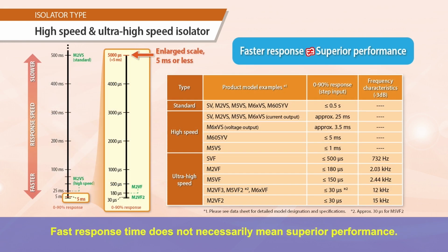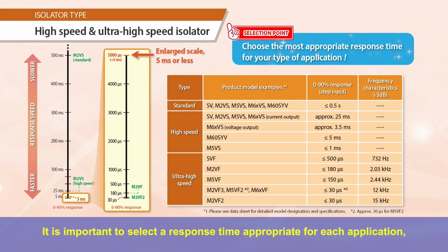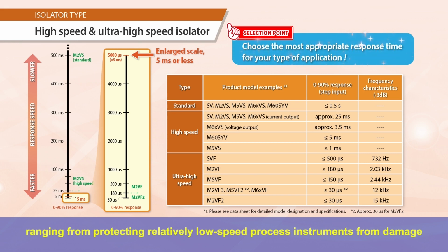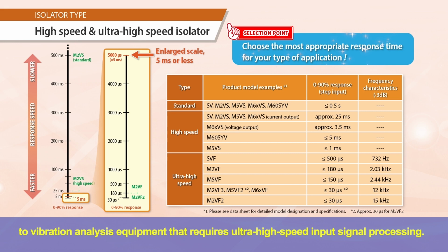Fast response time does not necessarily mean superior performance. It is important to select a response time appropriate for each application, ranging from protecting relatively low-speed process instruments from damage to vibration analysis equipment that requires ultra-high-speed input signal processing.